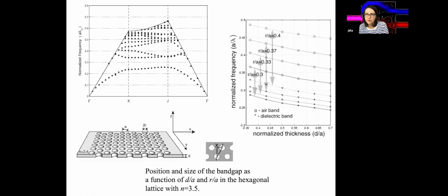You take one chip and then you change the dose during electron beam lithography, if you're using electron beam lithography, which spans the whole range of R, right? Because different doses, increasing doses, means that you would increase radii. And then after the processing, you can also do post-processing to control properties by some etching or deposition of the material and so on.